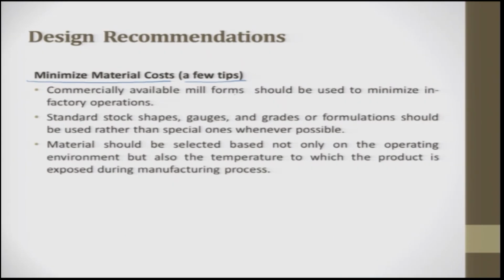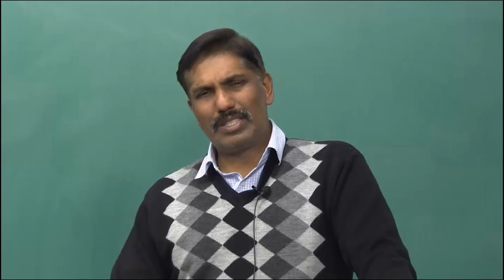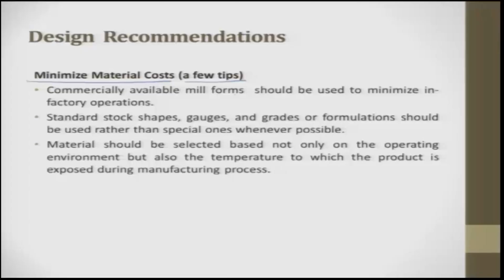And whenever you try to give a design, try to use the standards which are already available in the market. So, standard stock shapes, gauges, grades or formulations should be used rather than special ones wherever possible. That is why we try to standardize the screws and bolts M1, M2, M3, M4 and shafts.